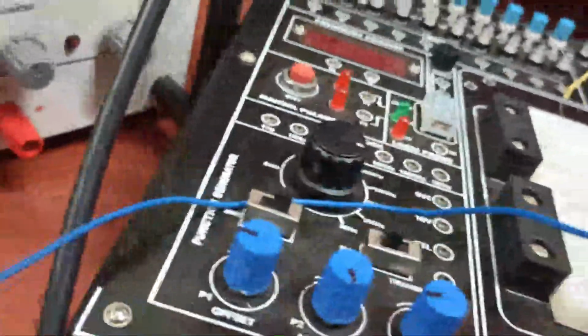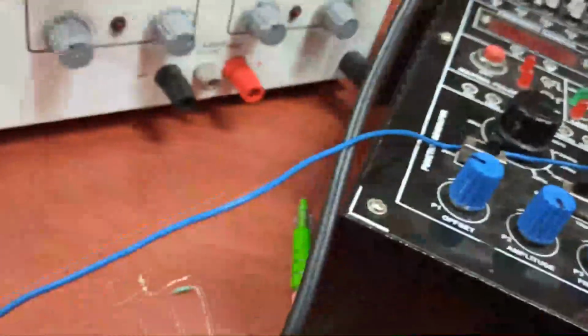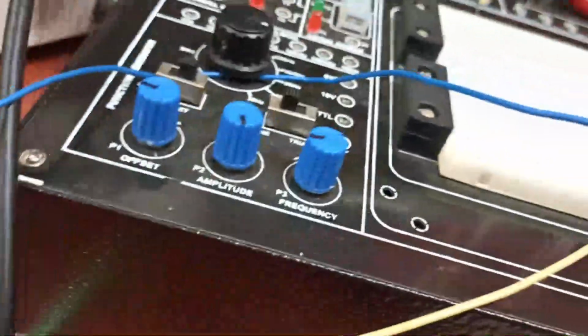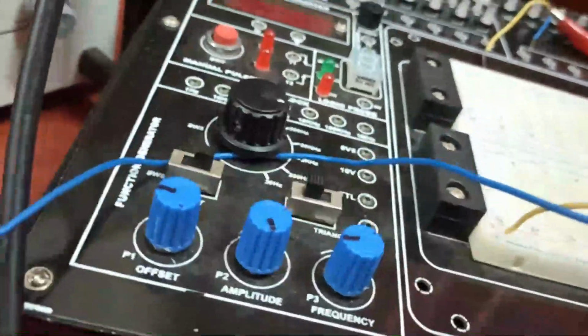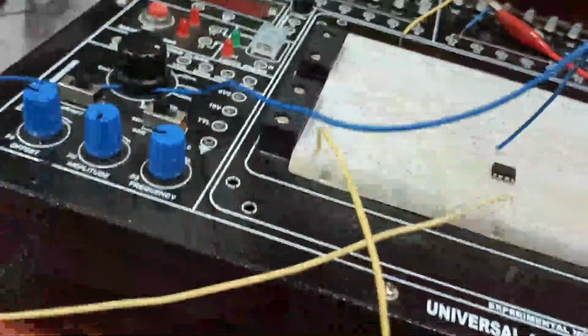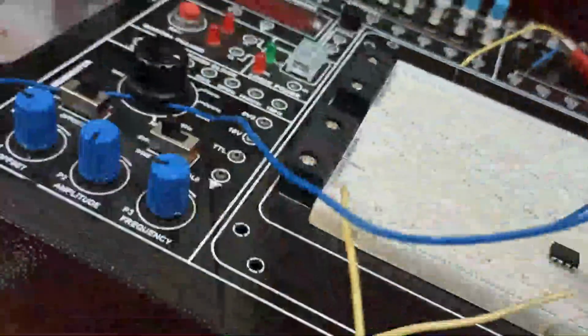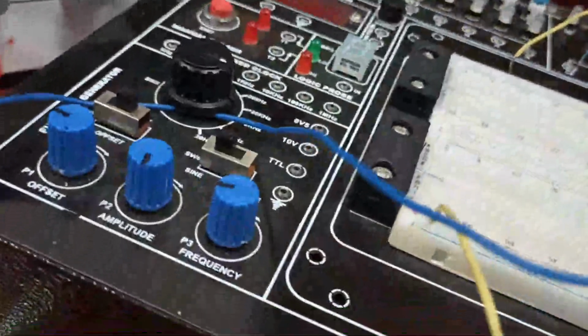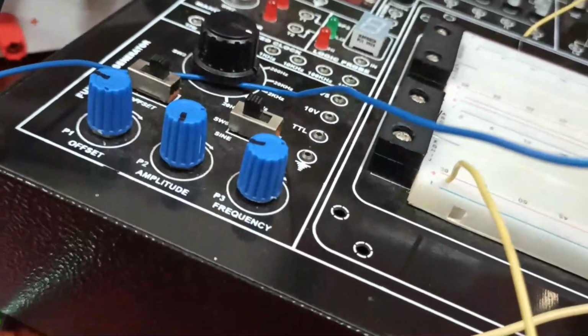And then I have to connect a resistor, and then there is a ground. I have to connect a ground to the common ground. I will connect the ground here. Okay. And then there is a 1K resistor which is to be connected to pin number 2. This is pin number 2. I connect a resistor 1K. I will connect it in this way.